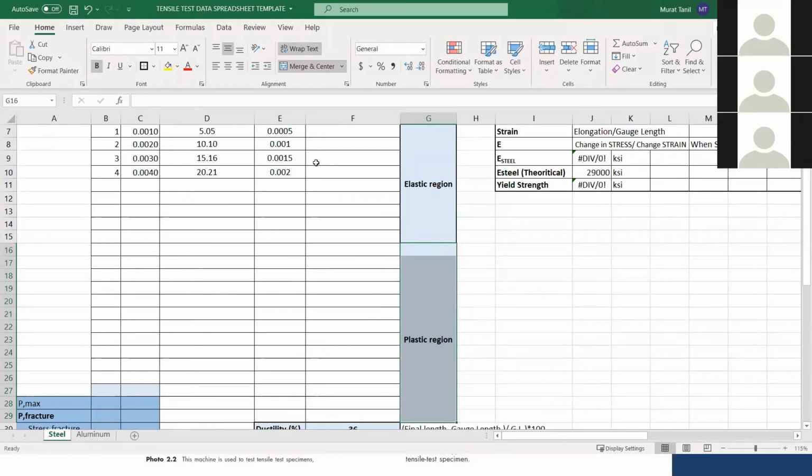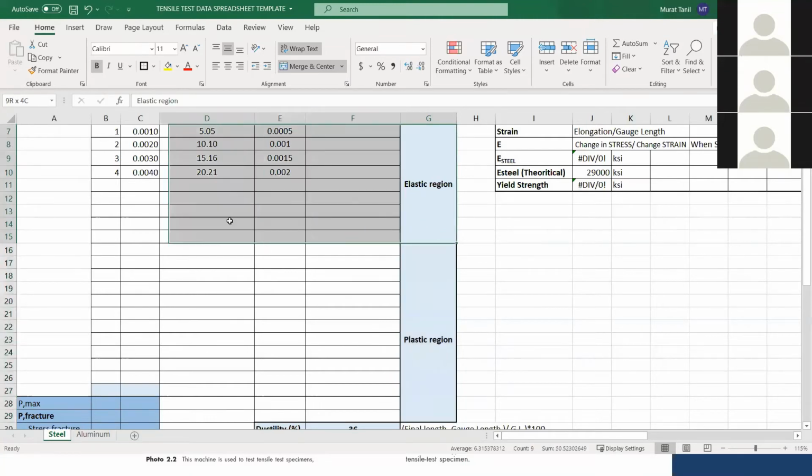If it does, then it's going to have permanent deformation. Then it's going to require rehabilitation, and it's going to be costly. So in order to avoid these issues, you work in the elastic region and you specify the maximum load that your material or your member can bear in the service condition. I don't know if it's clear, but as long as you are in the elastic region, you are safe.